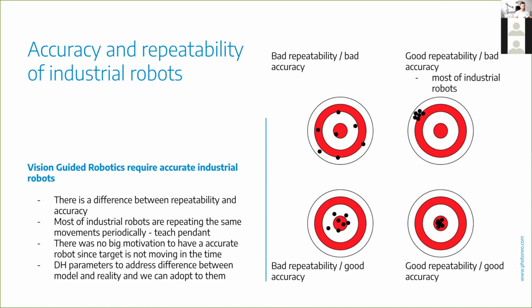If we increase the repeatability, we are still going to be inaccurate. This is the common problem with machines, because we tend to build them based on some CAD files or in general some blueprints, and then we assume that we build them correctly and perfectly, but the reality doesn't correspond to the math model. So we have bad accuracy but good repeatability, because this motor is going to the very same position every single time.